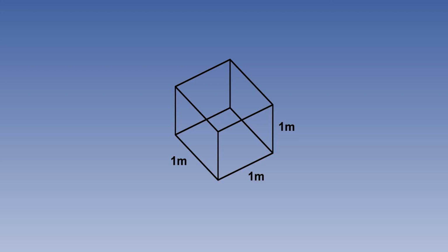If this cubic metre of air is completely trapped and brought to rest by an open-ended tube, the total energy will remain constant, but by virtue of being brought completely to rest, the kinetic energy is converted to pressure energy. This pressure energy is, for practical purposes, equal to half the density times the square of the speed, usually referred to as half ρ v squared newtons per square metre.